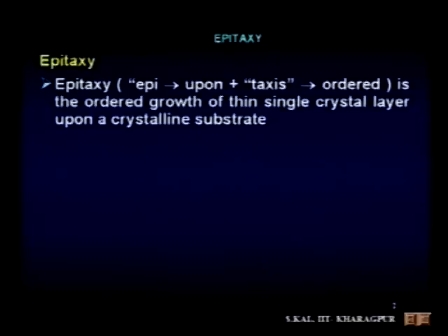other. So, in order to have isolation, you have to have an epitaxial layer, so that you can create islands of semiconductor single crystal layer in which you can fabricate devices which are isolated from each other. That means you can create isolated islands. So, for that you have to have an epitaxial layer, and epitaxy is an ordered growth of single crystal silicon, and the purity and uniformity of growth is very important in the epitaxial process.